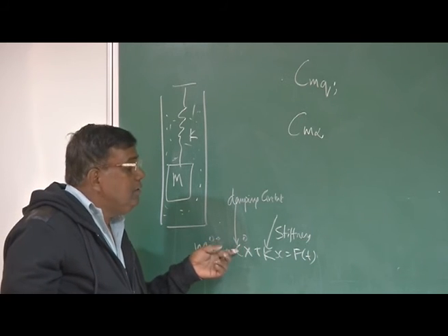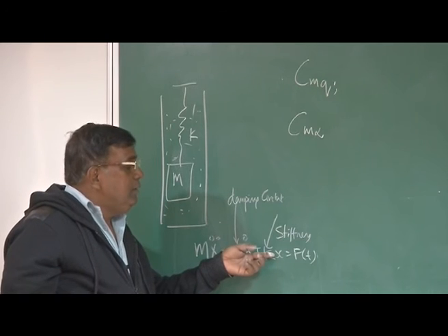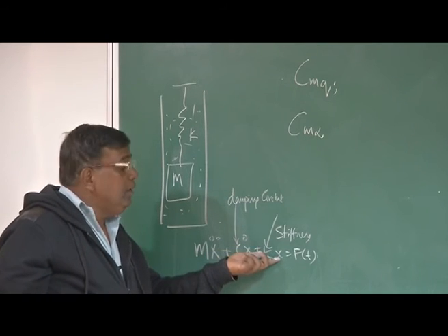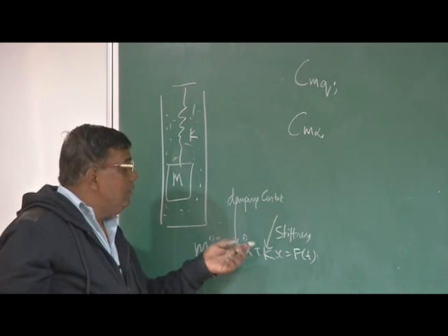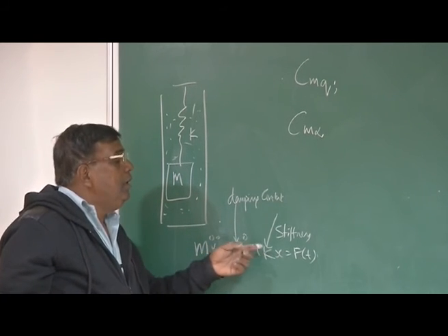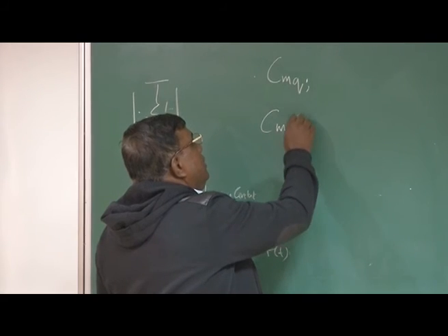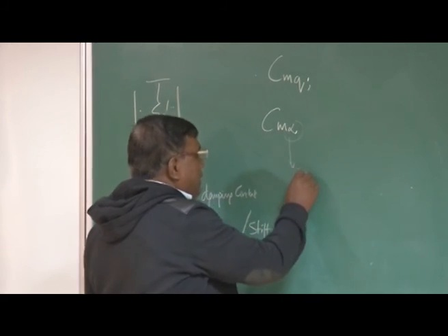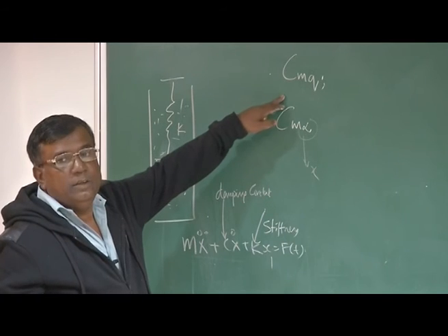So this constant is the damping constant. And the constant which tells you the amount of force or moment which is proportional to the displacement only, that is stiffness. So this is rate of change of displacement and this is displacement. Here you see when you are talking angular stability, alpha is like x here and q is like x dot here. It's a rate.